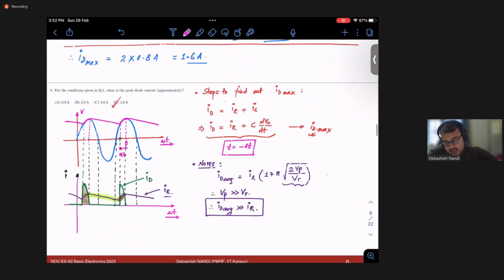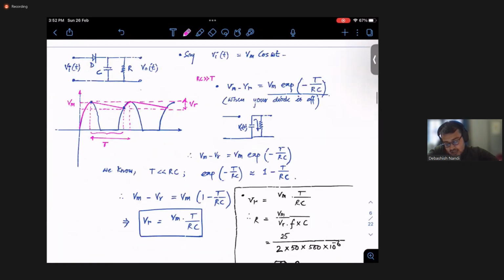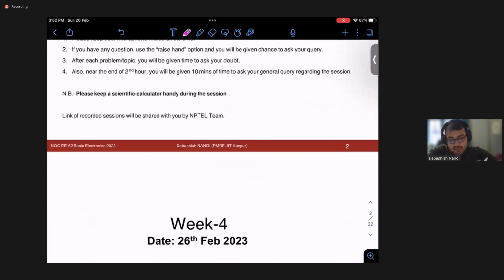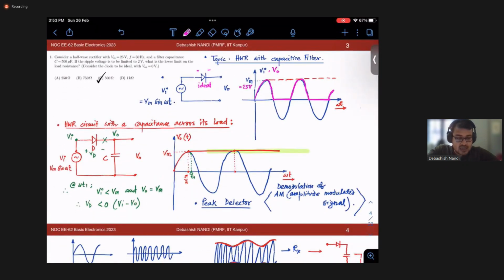This week we have discussed mainly the peak detector circuit, and first of all we discussed how an ideal half-wave rectifier will look, and then how a peak detector circuit will behave if there is no resistance present for the capacitor to discharge. Then it will store the DC value, and this is desired, because we have a constant DC voltage which I can feed to the next electronic equipment as a constant DC supply, right? DC means we need a constant voltage.